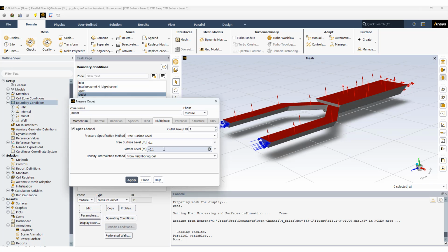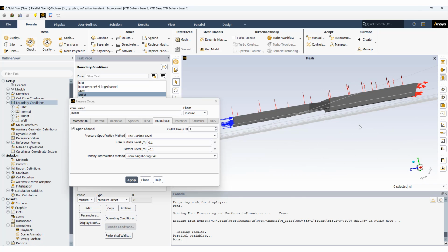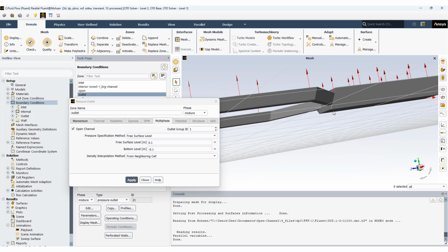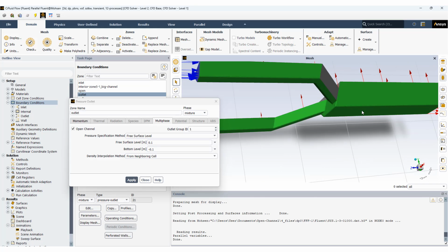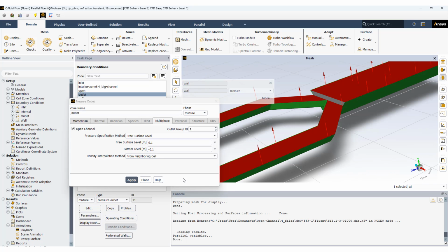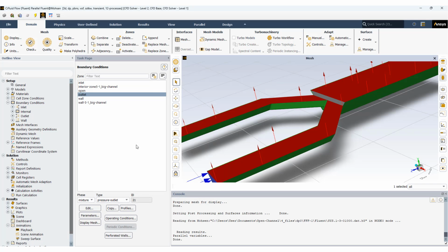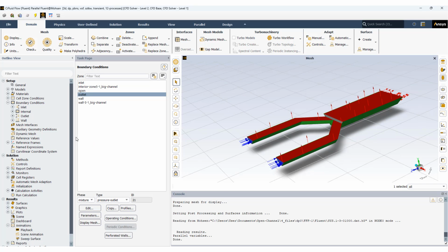Previously it was 0, but as you can see, because of more depth that I wanted, this bottom here, it is this part, it is at the level of minus 10 centimeter below the XZ plane. So I choose it -1 here. Okay, we don't want this here for now. And top faces opened.